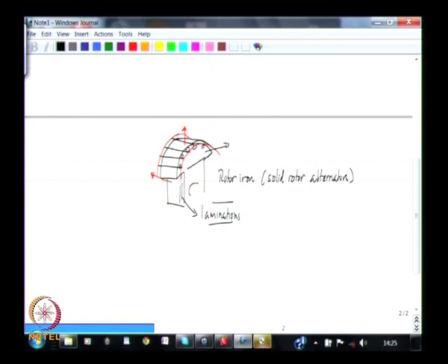But however, the rotor shoes, this area where the rotor pole shoes are there, that alone may be laminated in order to account for variations in the air gap and therefore induced EMF that may arise due to that because of effects due to stator slotting.